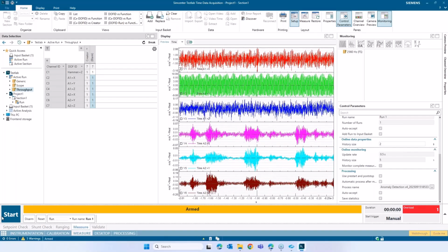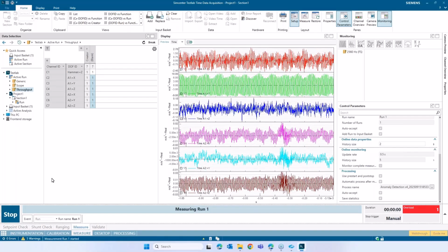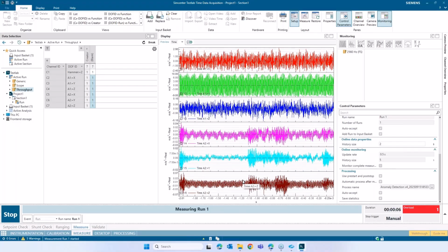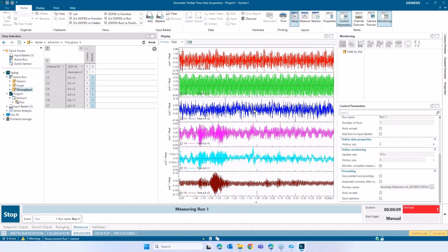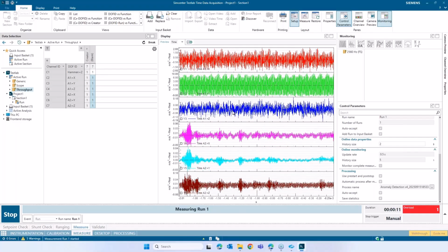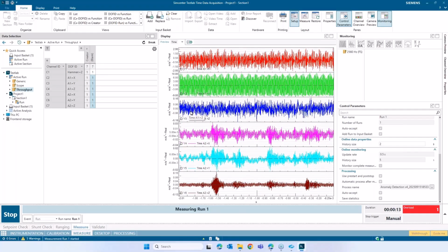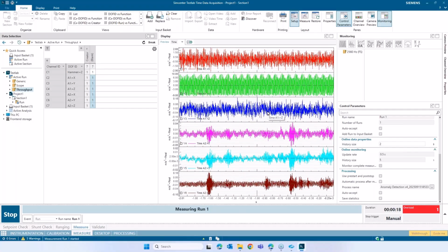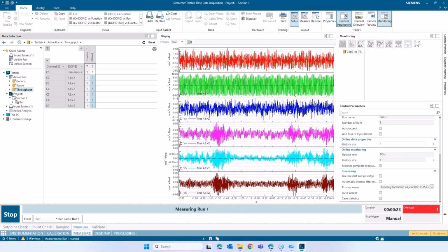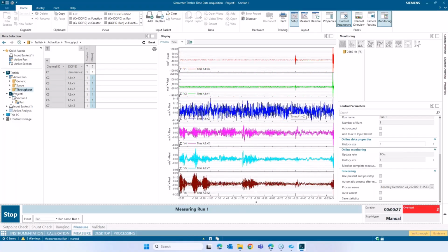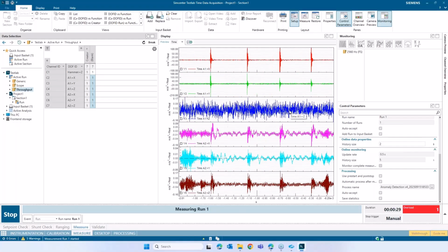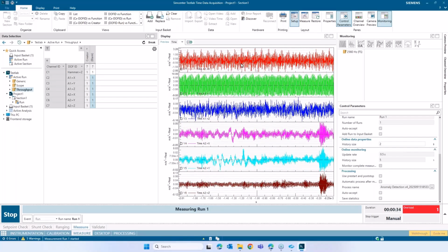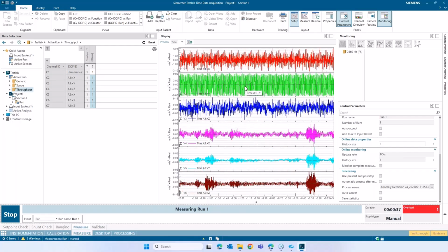Now I'm going to start the data acquisition. We can see the signals live as they are coming through, and we see some operational data. Things look okay. This channel, the blue one, looks suspicious because it's showing some low levels, and the shape is not so periodic, even though I'm measuring on a fan. I would expect something more regular. Then I'm going to tap near the accelerometer mounted on the fan, and we can see the increased vibration levels for that channel on the top one.